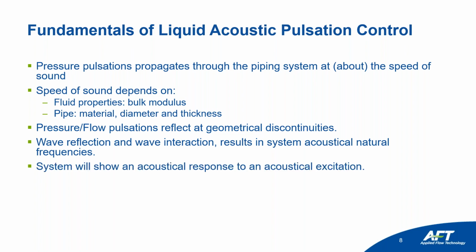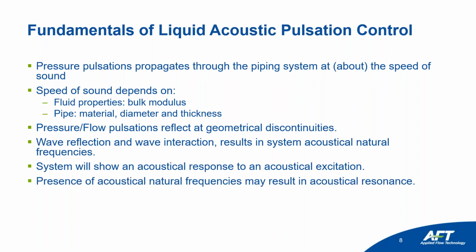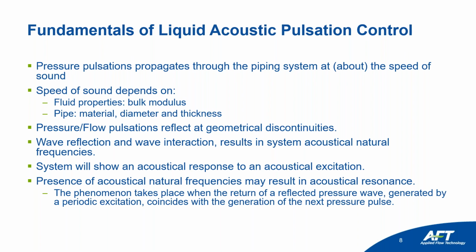The system will show an acoustical response to an acoustical excitation. The presence of acoustical natural frequencies may result in acoustical resonance. The phenomenon takes place when the return of a reflected pressure wave generated by a periodic excitation coincides with the generation of the next pressure pulse.